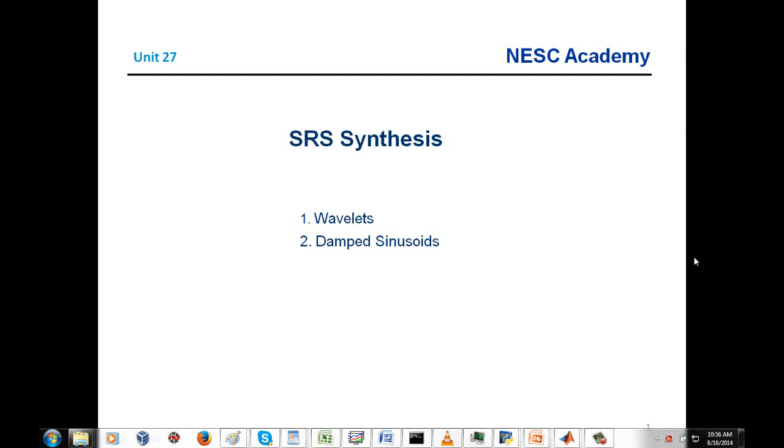So in the last couple webinar units, we've been discussing shock response spectrum. And a given time history has a unique shock response spectrum. But the converse is not true. In other words, given a shock response spectrum, there are multiple types of waveforms that can satisfy that SRS within some reasonable tolerance bands. And that actually gives quite a bit of flexibility to our testing.